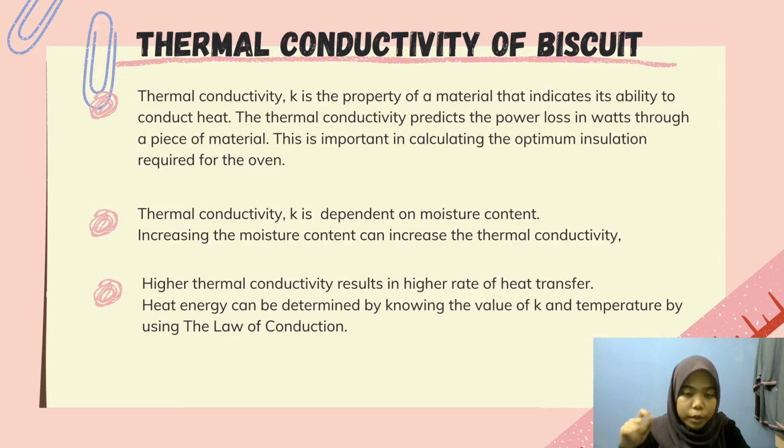From the result obtained, where the thermal conductivity of biscuit are determined by the line probe at various moisture content, it is proven that the reduction in moisture content can cause substantial reduction in thermal conductivity. So, from the line probe of the compacted biscuit, it shows that the thermal conductivity increases as the moisture content increases, and the thermal conductivity decreases as the moisture content decreases.